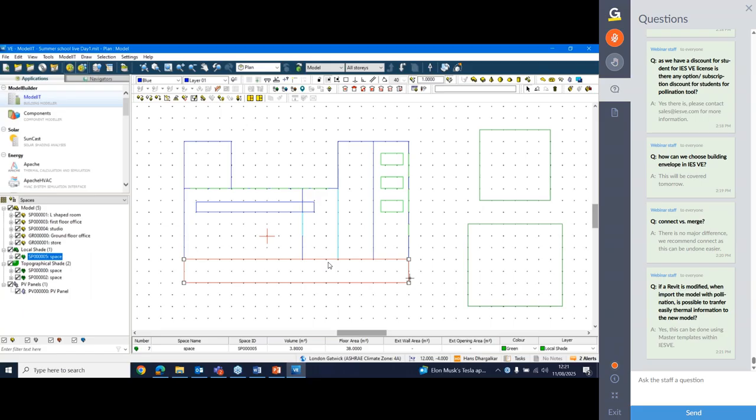So if you don't understand compliance, what I'm saying is probably gobbledygook. But if you are familiar with UK compliance, local shade is used to improve your actual building. So you have to class it as a local shade because it's not then included in the shading analysis for the notional building and the reference building.